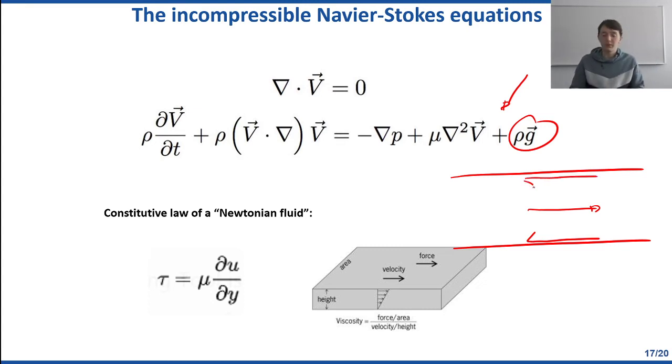So we have this shearing effect, that the flow is shearing across the boundary, producing a shear stress in the opposite direction as the flow, and at some point the shear stress should balance with the pressure that is driving the flow. Once we have this balance, then we have balance of linear momentum, and that's where you would get your mean flow prediction.